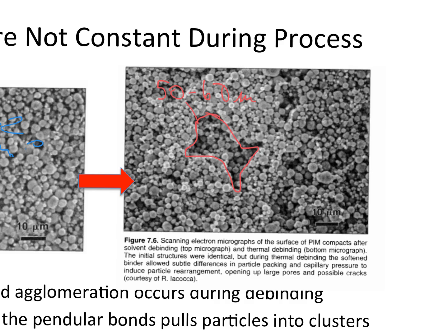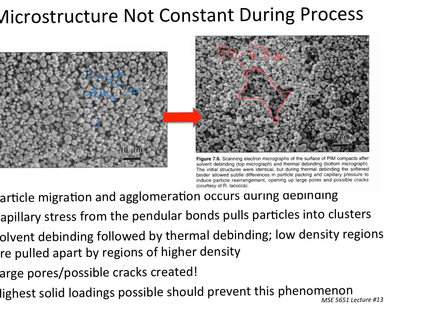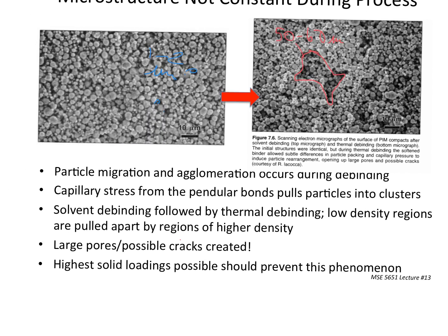Okay, so sometimes capillary forces are not our friend. And so we have this process of particle migration and agglomeration during debinding. Capillary stress from the pendular bonds, which a minute ago were doing good things for us, pulls particles into clusters, which is a bad thing. Solvent debinding followed by thermal debinding. Low density regions are pulled apart by regions of higher density, and you end up generating large pores or even cracks.